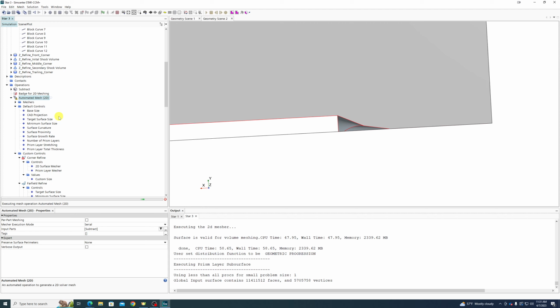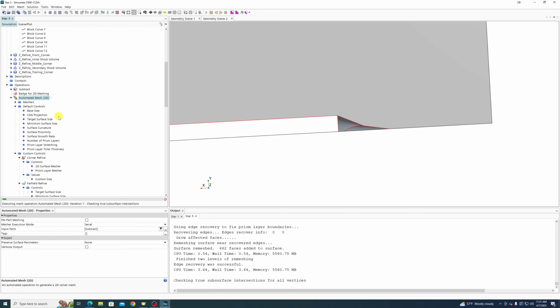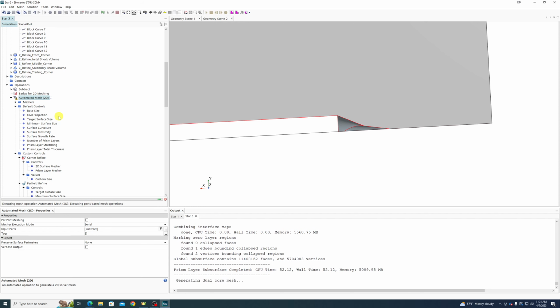Where I've run into it fairly regularly was when needing to model not just the air around a surface, but also model the solid body itself for thermal properties. And if you have a whole bunch of solid bodies, you need to run a surface mesh on all of them before you run a volume mesh on all of them. So it can be highly beneficial to run that surface mesh in parallel, in concurrent mode, and then run the volume mesh in parallel to help save some time.